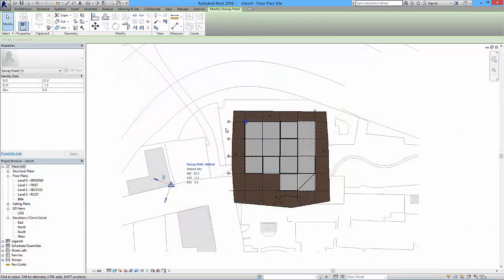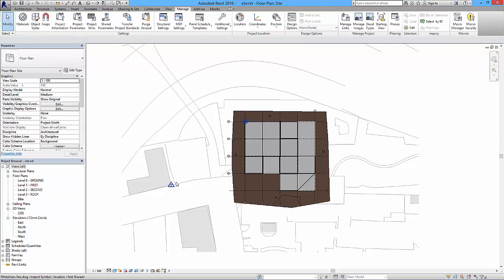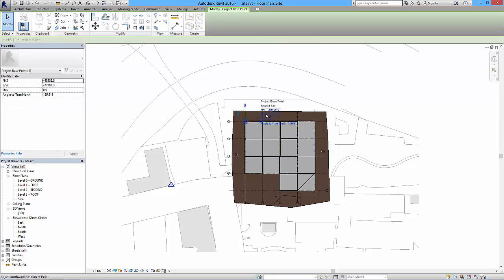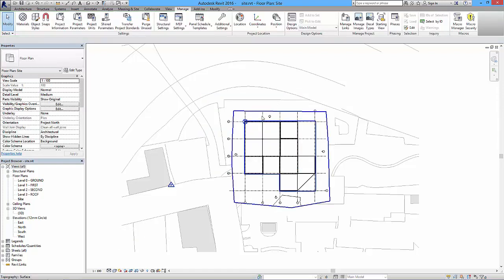I'll just go back over to a Revit file. So that's replicating that. So there's two basic points, and now these are usually sitting on top of each other when you open up a new drawing, so they don't have any real relationship. It looks like there's one symbol, but there are in fact two. And if I select this one, this is the project base point. I'll just go back to hidden line mode and ignore that so we can see what this thing says.